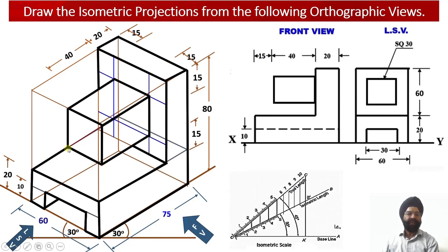So this way we have been able to obtain the isometric projections of a solid, while the orthographic projections of the solid were available with us. So this is the procedure regarding the construction of the isometric projections of the solid, by dividing it into a number of elements and then by integrating those elements into the combined solid, right?